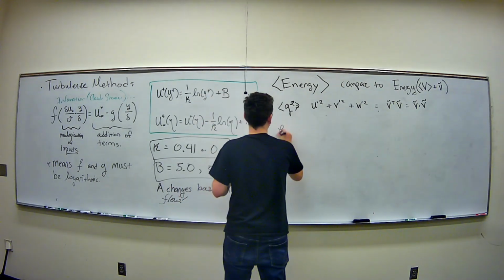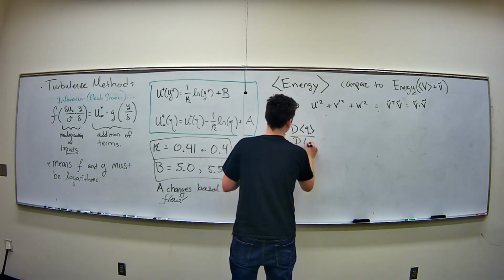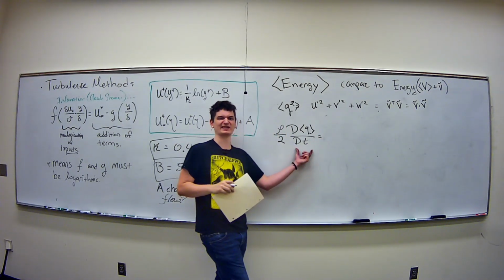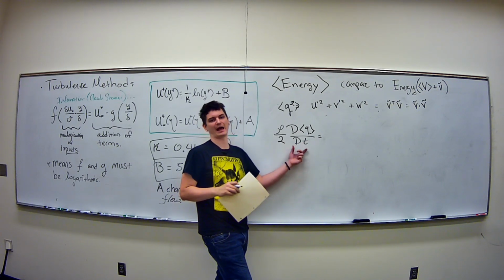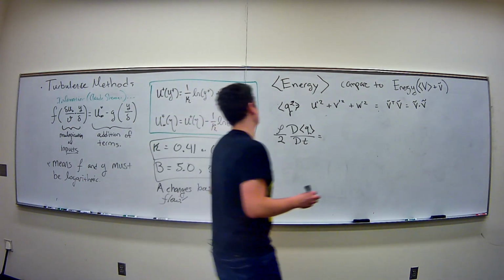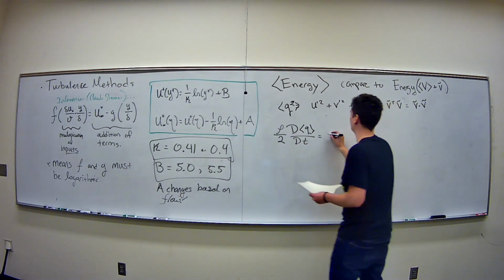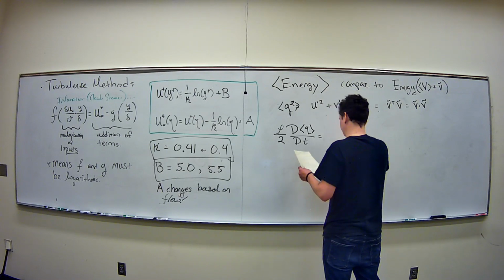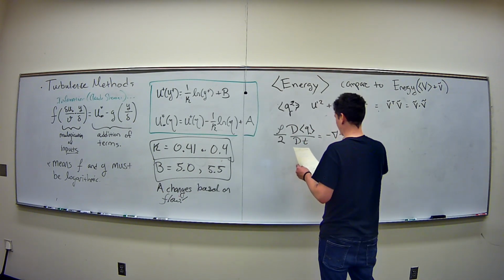And then you get this equation. So there's a capital D, Q over Dt. This is the material derivative of that turbulent kinetic energy. I hope you all know capital D, Dt as an operator. So this is how to model how the turbulent kinetic energy changes around in the field. And you get all of these terms. I think one of these is wrong symbolically, by the way, but it doesn't quite matter for interpretation.